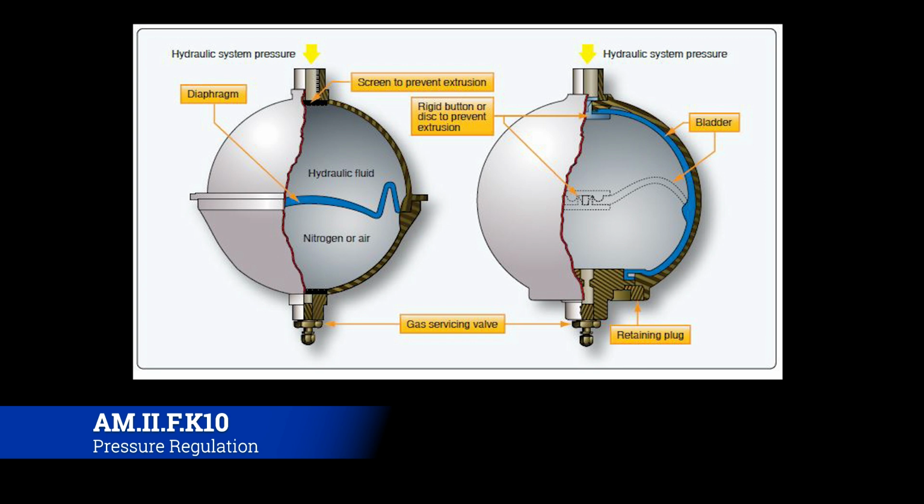All right, so what does that exactly mean? Essentially, the accumulator gathers up a bunch of hydraulic fluid and pressurizes it through air. Usually you'll have a bleed air system that ties into it, or, depending on the aircraft, some source of pressurization of that air on the other side of the diaphragm.